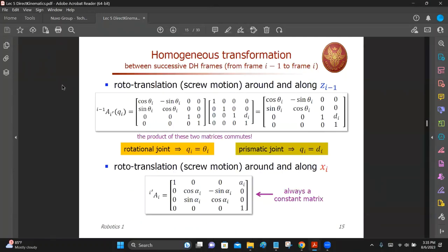Now you are familiar with the geometry. Now it's time to describe these operations mathematically. So now I'm trying to write down the transformation matrix that we have learned in previous weeks, right? Try to relate joint coordinate frame i minus 1 to i. So I take i minus 1 as the reference for the previous and i as the new.